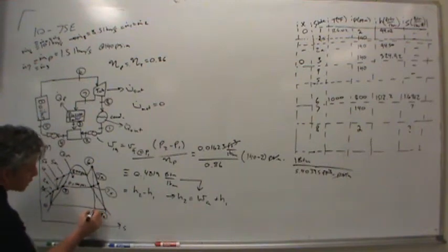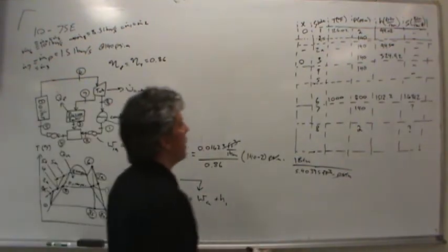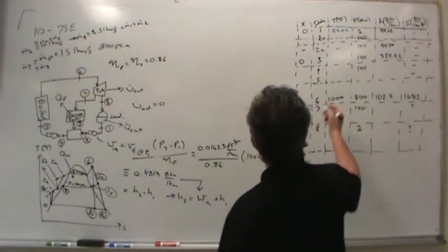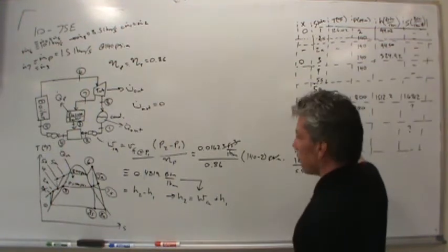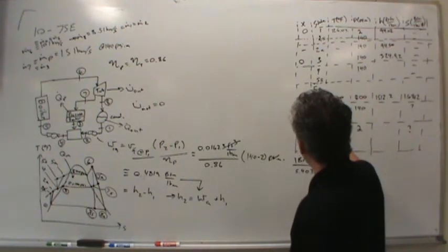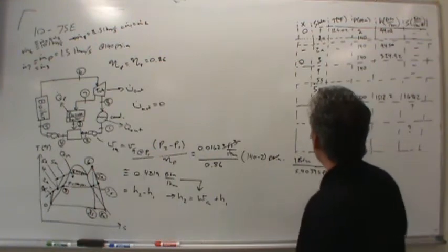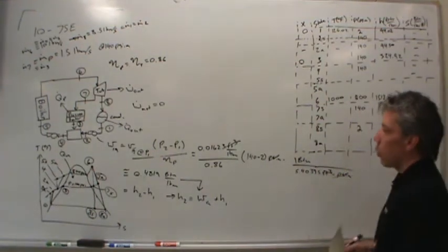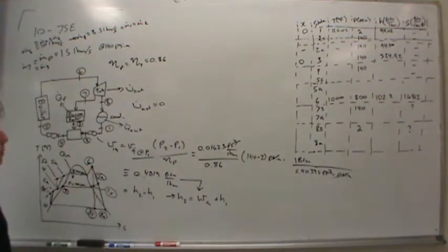State 8A, and a state 7 isentropic. I'm sorry, state 8 isentropic. So that's why I left some space here, because there's a 5s state and a 5 actual state. There's a 7s state and a 7 actual state, an 8s and an 8 actual. These S states are where the pumps and the turbine should end up. But the actual states are where it actually ends up.